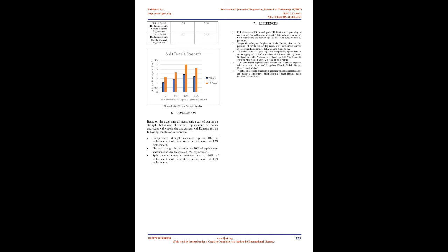Concrete mix design. Based on trial mixes for different proportions of ingredients, the final design mix was prepared for M35 grade of concrete as per IS 10262:2009. The W/C ratio was considered as 0.4, with varying percent of cupola slag and bagasse ash, and design was done. The different specimens as per the requirement for test were cast. The specimens were tested after 28 days of curing. In each category the specimens were tested and the average value is reported in the form of graphs.